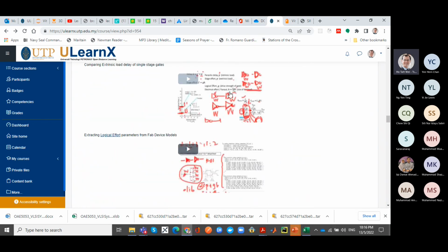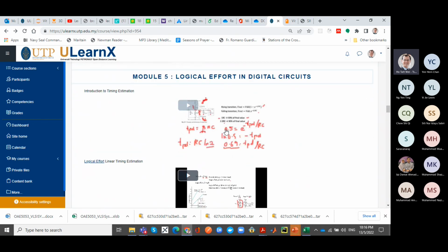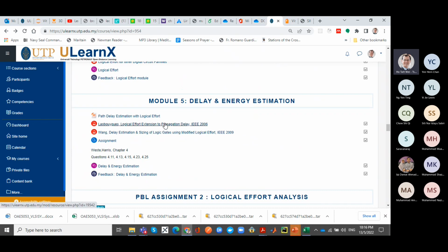So for logical effort, you have to go through the theory of the estimate for a single gate first, then for what we call a logic path, right? And again, this analysis you're not going to do for every single logic gate in the design. What usually happens is you'll find what we call the critical and near critical paths. These are the list of slowest logic paths in your circuit.